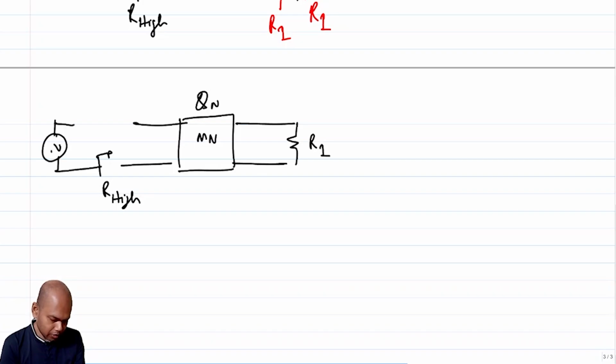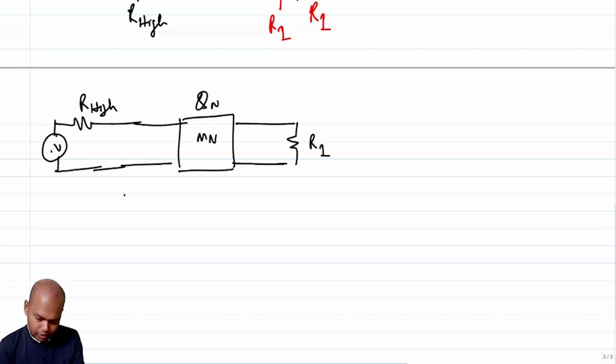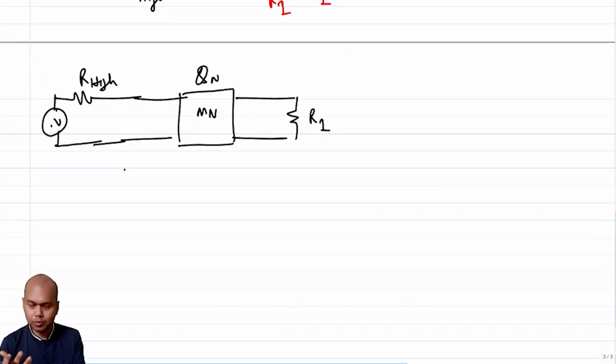The whole purpose is that I have a resistive source with resistance R high, and I want to match it to Ri, right? So assuming that the matching network is lossless, which we were essentially assuming while trying to figure out the Q factor of the network, right?